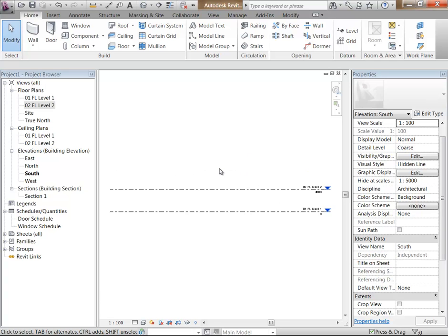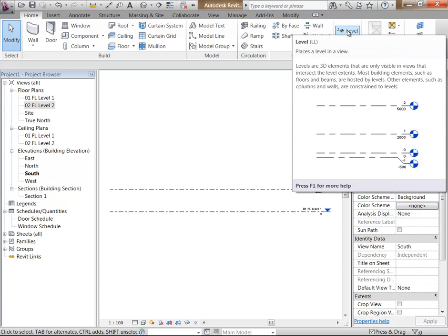And that's one of the common misunderstandings with Revit when you first start working with floor plans, mixing them up with levels, because they are different. Level plans can be associated with levels, but you can actually have levels without plans. So they're not the same thing, but like I said, it's good to have them associated, and then if you need to, make copies of the plans if you want different names.